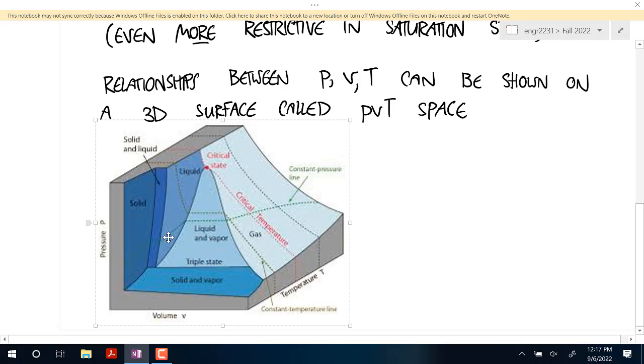Okay. And so if you follow that constant pressure process from the high temperature, start over here where my cursor is, and say you're decreasing the internal energy in this material. If you trace along this line, the pressure is staying constant, the height is staying constant, but the temperature is going down, and the specific volume is going down.